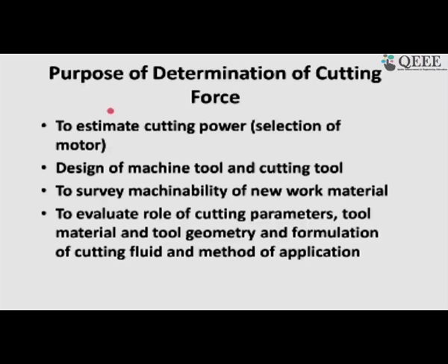So, accordingly we have to have proper design, and there cutting force has an important role to play. Similarly, for the cutting tool, the tool holder should not bend, should not have deformation, or should not even break. The cutting edge may break if the force is quite high. So, for that also the cutting tool geometry and size has to be designed. For that we need to know the cutting force.